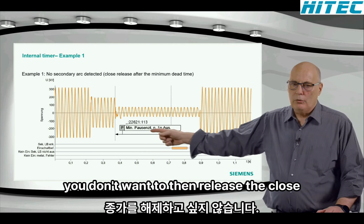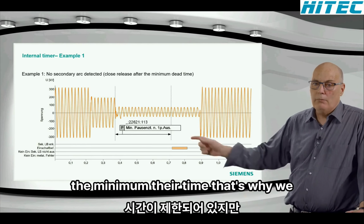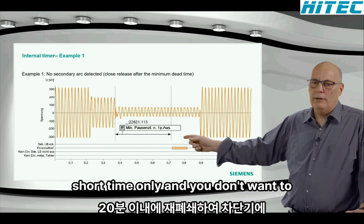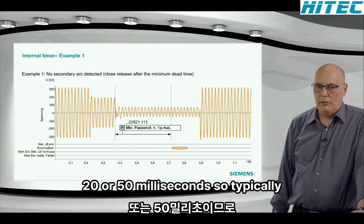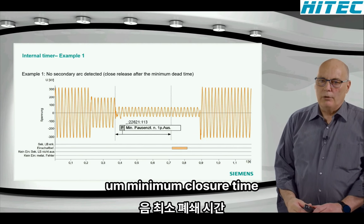So you don't want to then release the close basically after 50 or 70 milliseconds. You need to wait the minimum dead time. That's why we have a minimum dead time, because it could be that the secondary arc is there for an extremely short time only, and you don't want to stress the breaker by reclosing within 20 or 50 milliseconds. So typically around about 150 millisecond minimum closure time.